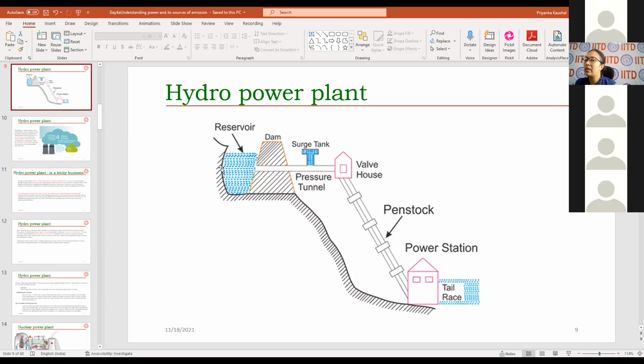Now, as I told you, in all these calculations, we do it per unit of electricity. Let's assume it is generating 100 kgs of GHG gas, and you are producing 100 units, right? So the ratio is 1:1. For 1 unit of electricity, I'm releasing 1 kg of GHG gas. Now, if I start producing more electricity, instead of 100 units, I have a very advanced technology, let's assume very sophisticated turbines, which can now produce 150 units of electricity. So this GHG is now spread over 150 units, right? So it will immediately reduce my carbon footprint, or my GHG footprint, per unit of electricity. So this is important, right?